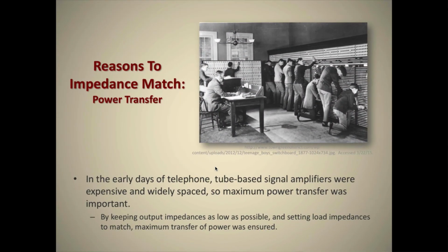Another important thing, and the reason they matched back in the day, was that matched impedances guarantee the most efficient power transfer. That's kind of a complicated statement to unravel. A better way to say it is they guarantee the most efficient power transfer in a tube circuit paradigm. In the era of tubes, having matched impedances between source and load was the most efficient way to transfer power.